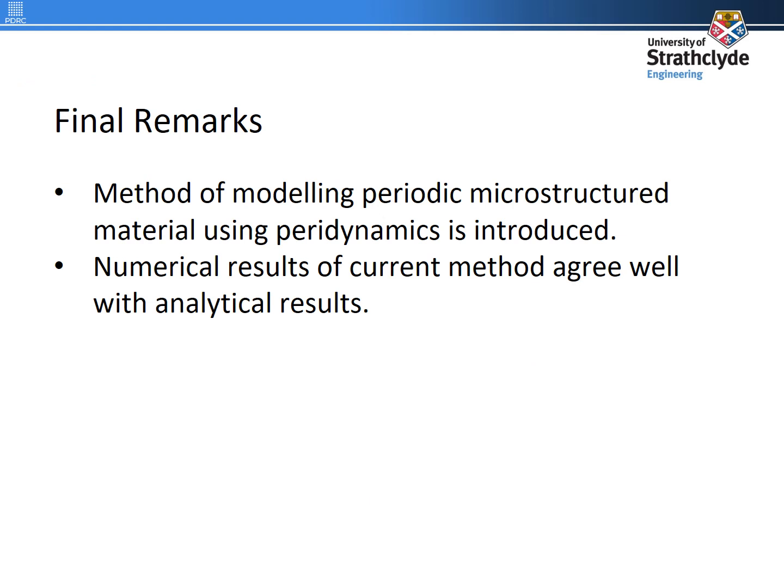During this presentation, we introduced the method of modeling periodic microstructured material using ordinary state-based peridynamics. Then we verified our approach, and very good results are being observed. Next, we can further investigate different damage types and their influence on the effective material property of the unit cell.